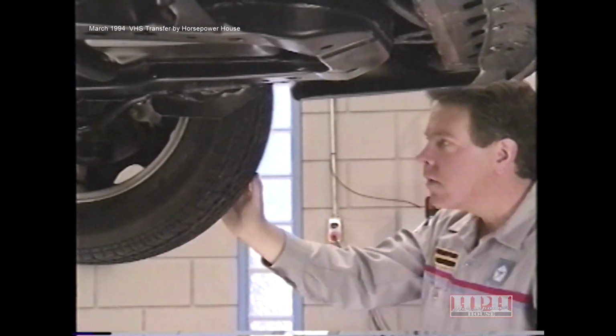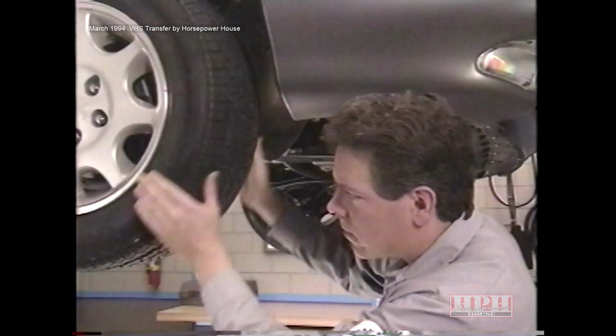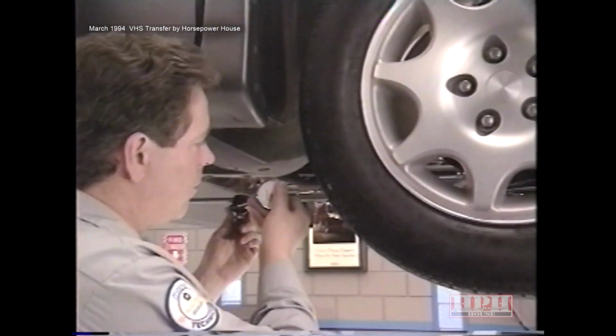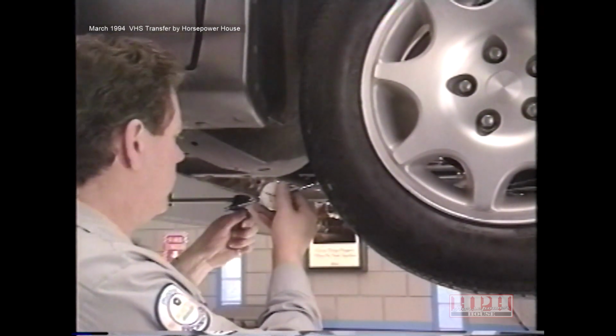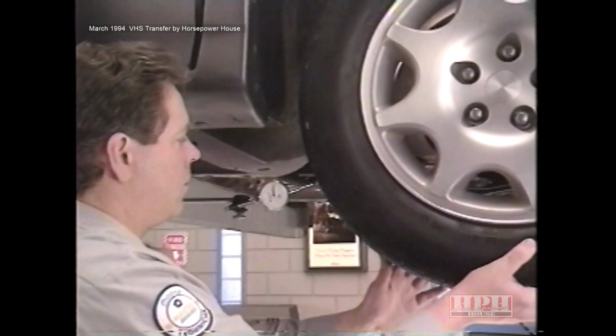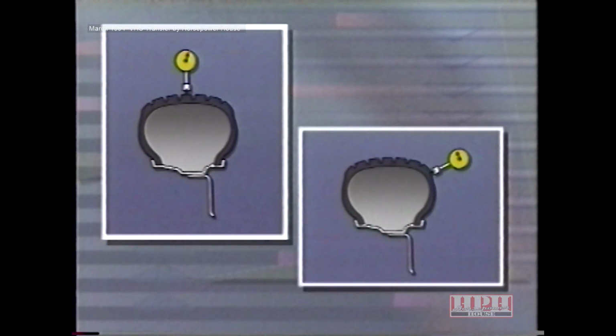We'll first visually check the amount of runout from the front or rear by spinning each wheel by hand, looking for obvious signs of runout. In this case, the right front tire showed obvious signs of runout, so we'll measure that wheel first. In less obvious cases, it might be necessary to measure every wheel. Using a dial indicator, we'll measure radial and lateral runout.